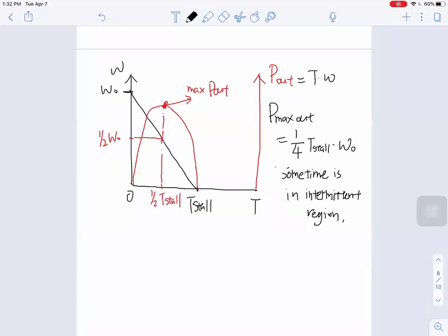And here, I think it's a good time to talk about the efficiency of the motor. Efficiency of the electric motor is equal to the power output over the power input. The power output can be torque times omega. The power input, which is your electric power, is current times voltage, and times 100%. So that's the efficiency.